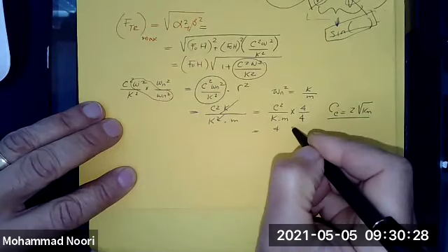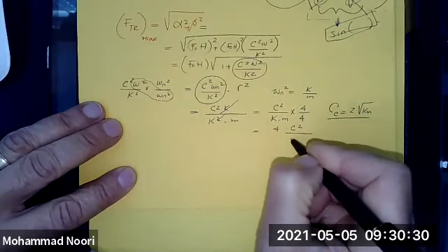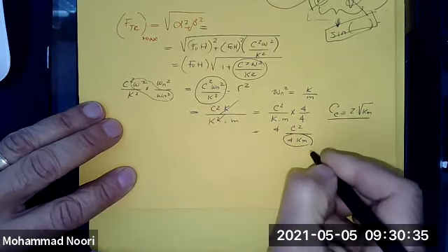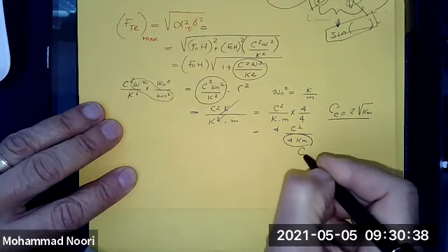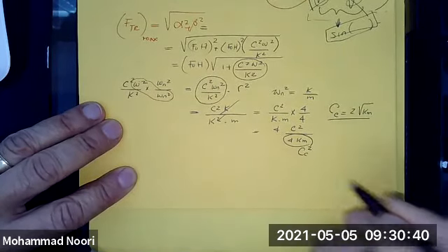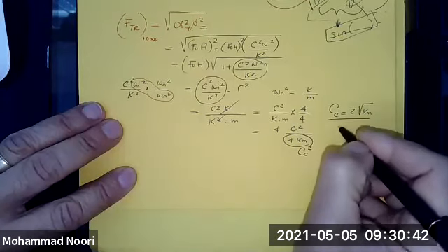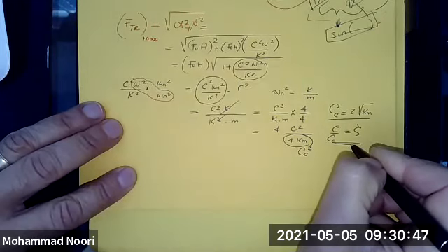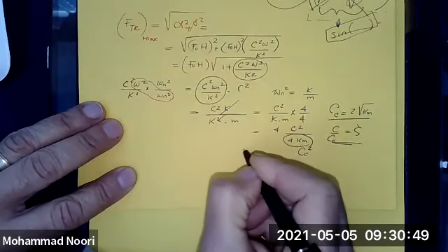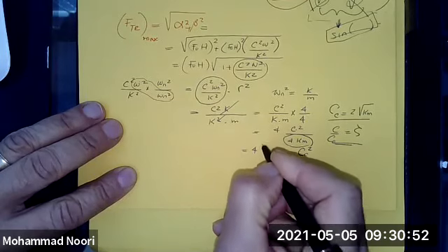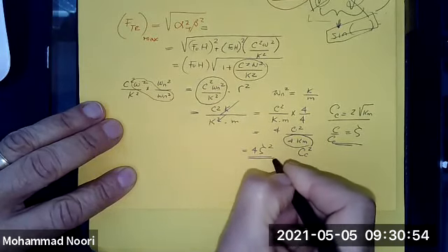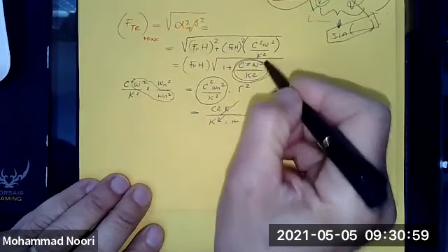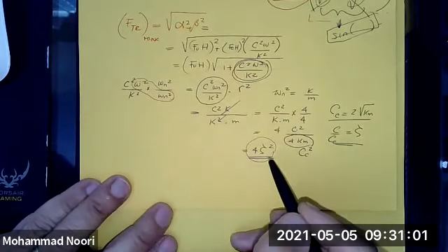I have 4 C squared over 4 Km. So in other words, I have C critical squared. Or the ratio of C over C critical is what? Damping ratio, right? So this is then 4 zeta squared. Here we go. So I converted this to this nice term.